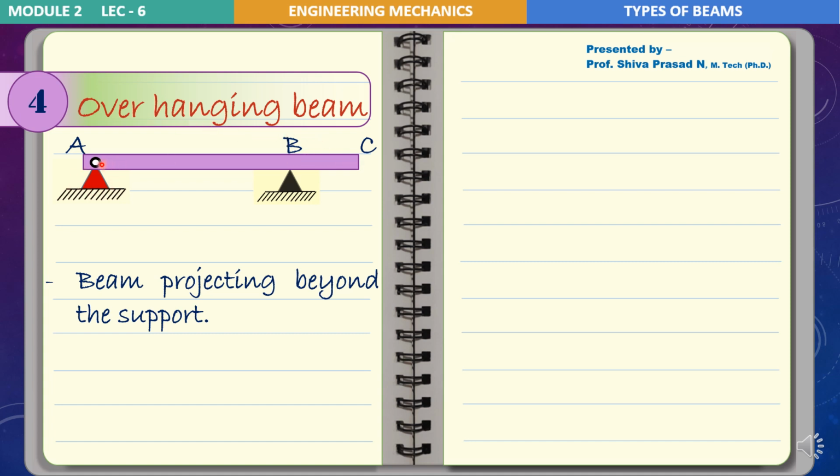Instead of a hinged support, I can have a simple support. Instead of a simple support at B, I can have a roller support, any other combinations. So just let's go our routine way, I'll draw the support reactions. So vertical reaction at A and horizontal reaction at A. Again, coming to point B, I have a vertical reaction only. That is, the reason is it is a simple support.